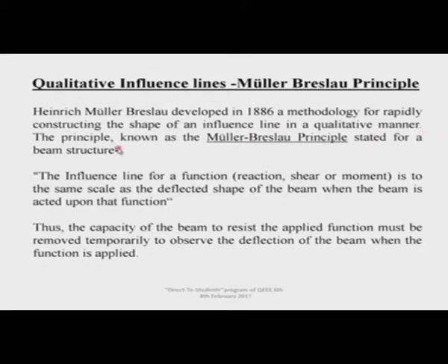The principle known as the Muller-Breslau principle, stated for a beam structure, let us have the statement first, then we will discuss what it means, then whether from our perception we can feel that. We need to feel the structures, otherwise it will be difficult in future. So, the influence line for a function, reaction, shear or moment is to the same scale as the deflected shape of the beam when the beam is acted upon by that function.